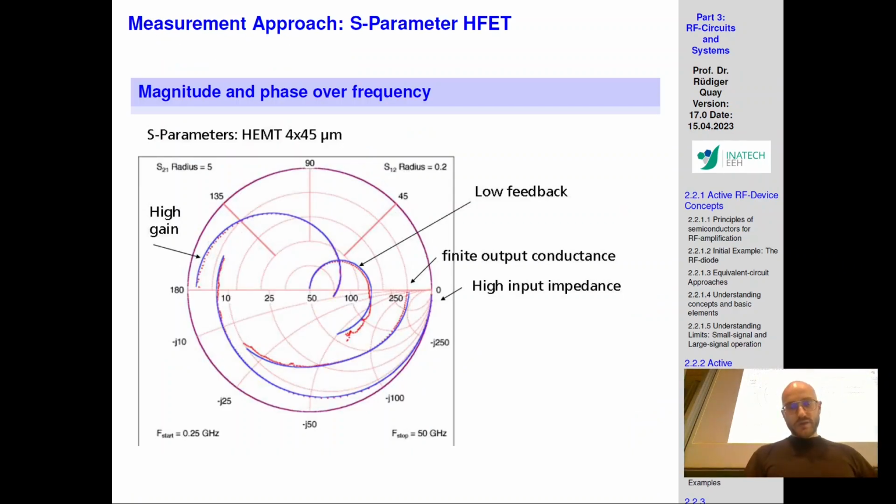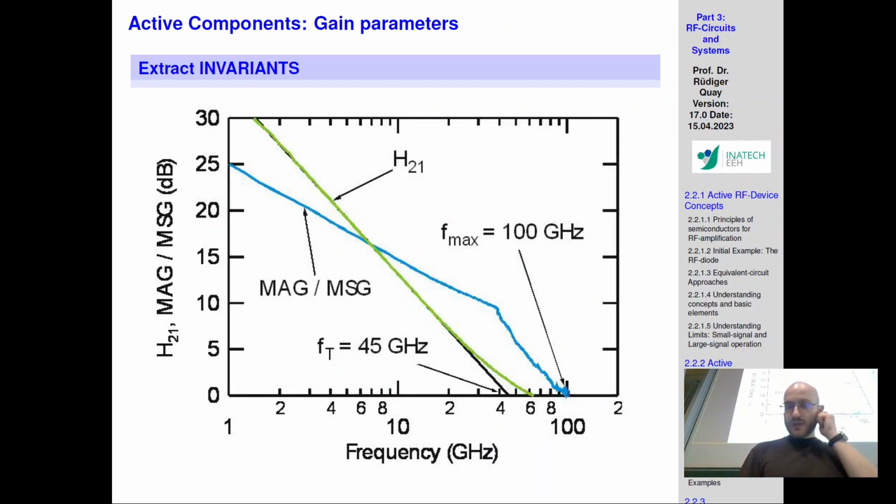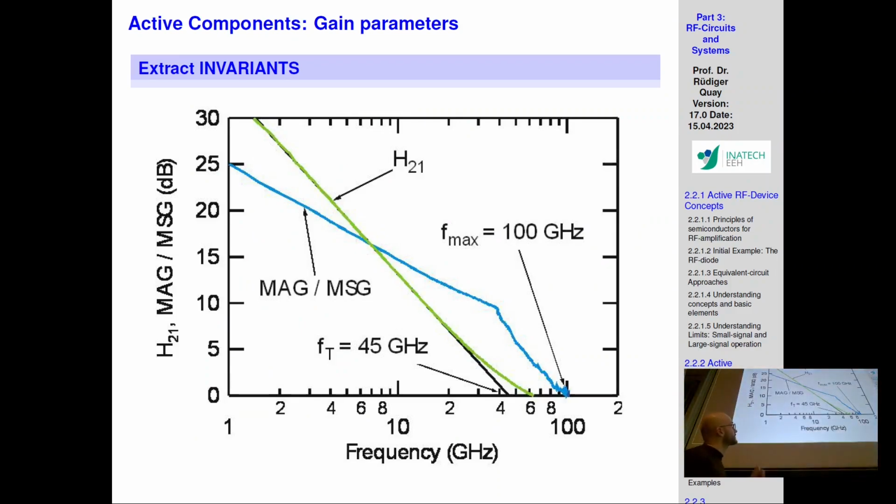We saw the matching of the Smith chart. We talked about FT and Fmax. I've mentioned it a few times here. Whereas maximum stable gain and maximum available gain. What does that mean, and how is that defined in terms of the K factor? The K factor was this special formulation that allowed us to define whether our device is unconditionally stable or not.